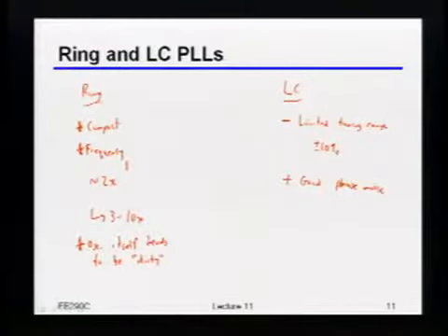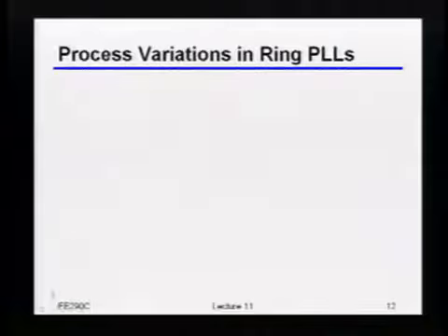This is something we'll get into in a lot more detail next, but if the ring oscillator is pretty dirty, that means you really want as high a bandwidth as you can in your PLL loop, right? Because the higher the bandwidth of the PLL, the more it'll reject the noise coming from that ring oscillator.